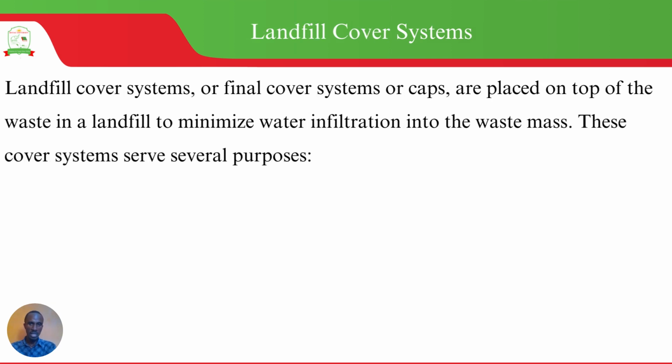So by effectively collecting and managing the leachate, the potential of contaminating groundwater or the surface water is significantly reduced. Like we had said earlier, we have landfill cover systems, which are the final cover systems that are placed on top of the waste in a landfill to minimize water infiltration into the waste mass.